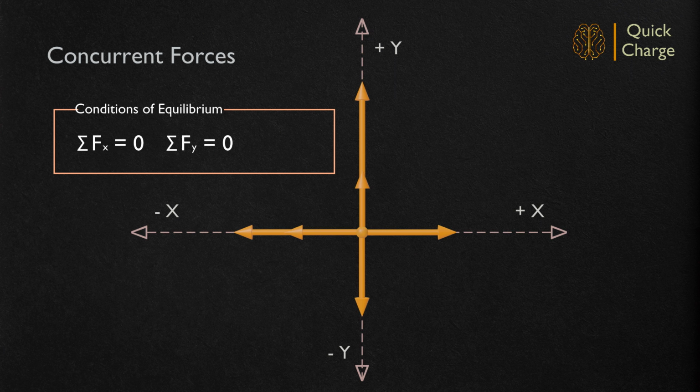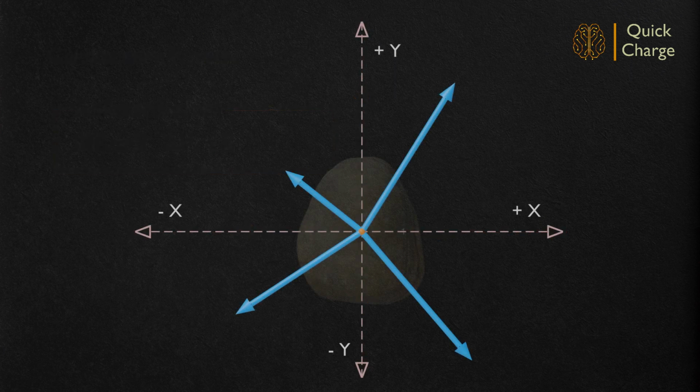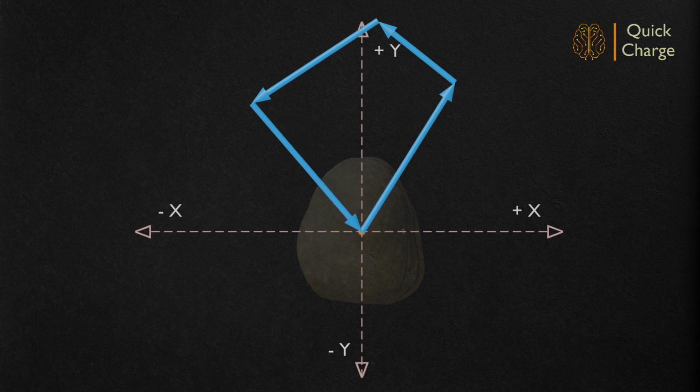Earlier, we have discussed graphical methods of composition of forces. While using graphical methods, how do we understand that a concurrent system of forces is in equilibrium? Let us find out the resultant using polygon law of forces. Yes, the forces form a closed loop. As per the polygon law, the distance from the start point to end point defines the magnitude of the resultant. So a closed loop indicates zero resultant and is in equilibrium.